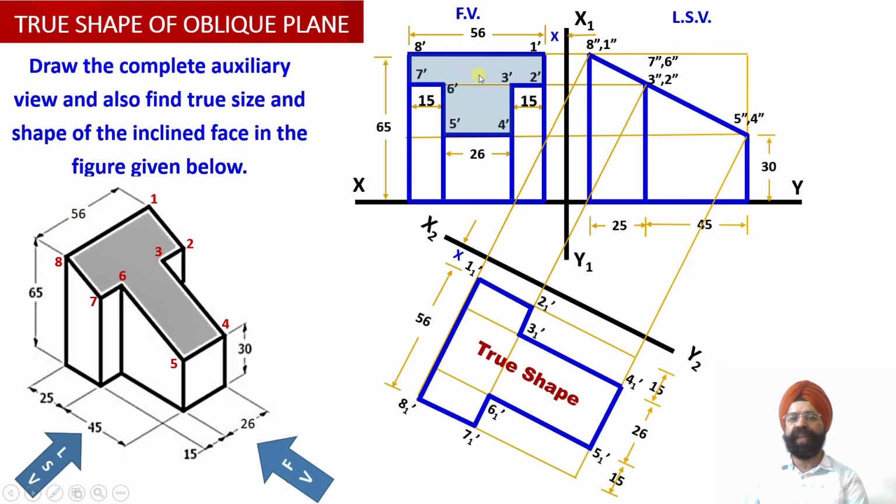So we observe that the apparent shape which was obtained in the front view is much shorter than the true shape of this solid. This is because we had this edge view which was inclined to the vertical plane over here. So we were not able to get the true projections of this particular section cut surface onto the plane of projection over here.